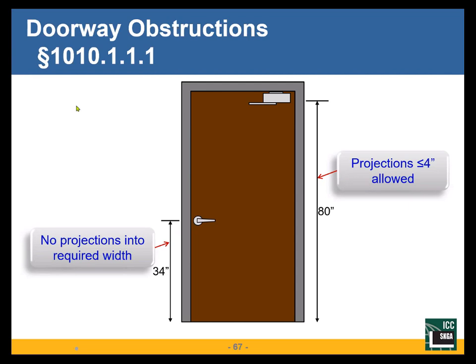Floors with mixed occupancy groups. How do you measure maximum allowable dead end space? Okay. When I'm looking at dead end corridor, and I have an allowance for a different occupancy, this occupancy says for this occupancy, I get 50 feet dead end corridor. This occupancy says I get 20 feet dead end corridor. If they're both using the same corridor system, we use the most restrictive.